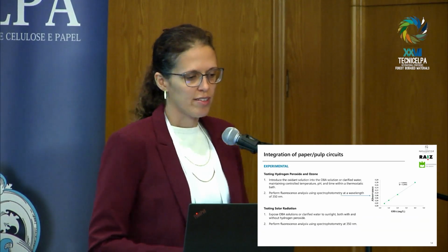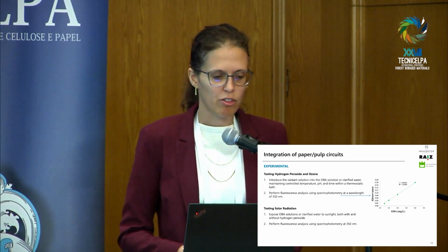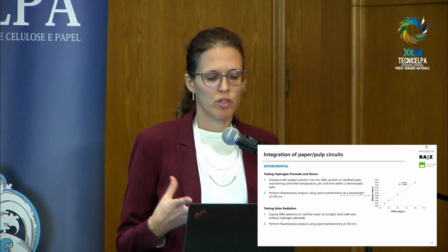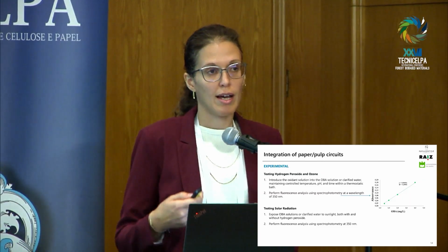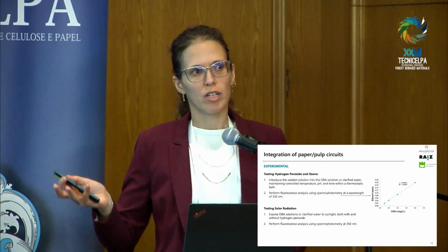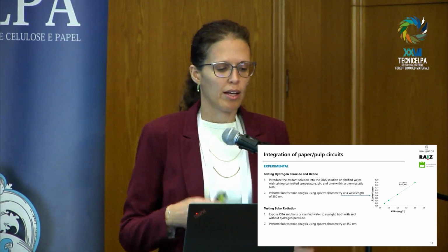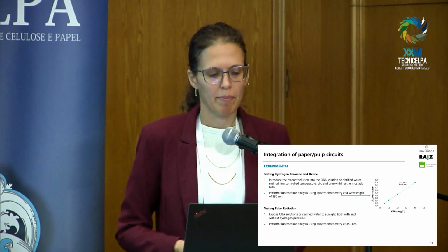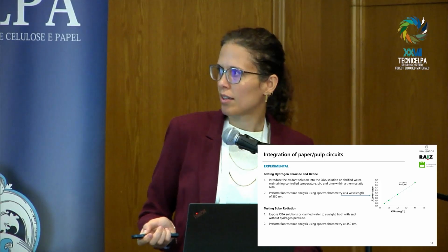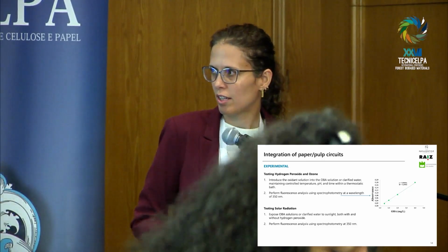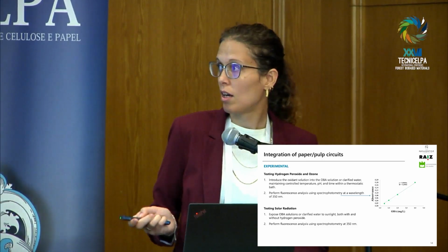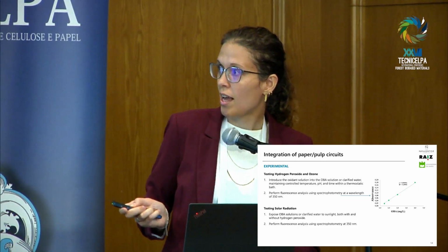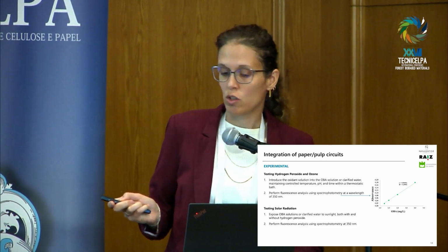We also tested other chemicals like hydrogen peroxide and ozone. This time we add them to the solution, a pure OBA solution or the real clarified water at controlled temperature, pH, time, and then we analyze the liquid by spectrophotometry at a wavelength of 350 nanometers, because we saw that there is a linear correlation between the absorbance at this wavelength and the OBA concentration.